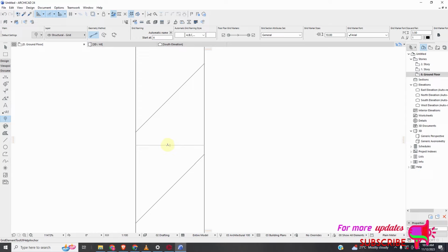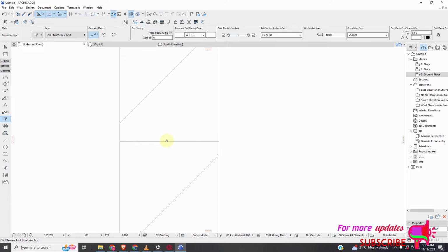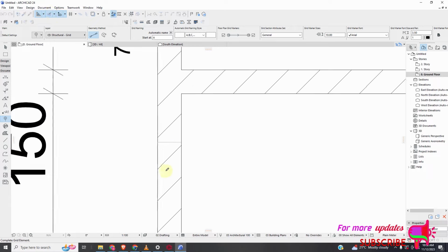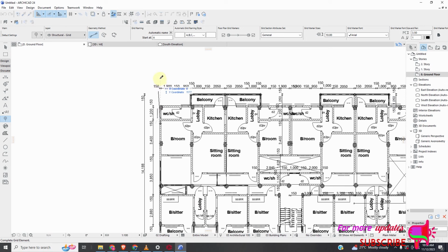When my grid line tool is active, it is just snapped at the midpoint there, and that is because this one is turned on. You can see this one, snap guide and point. If I turn this off, then I'm not going to be able to snap. So I'll just turn it on. Okay. It is snapped at the midpoint. That tick, then I'll just drag my grid line, which is also snapped at vertical.